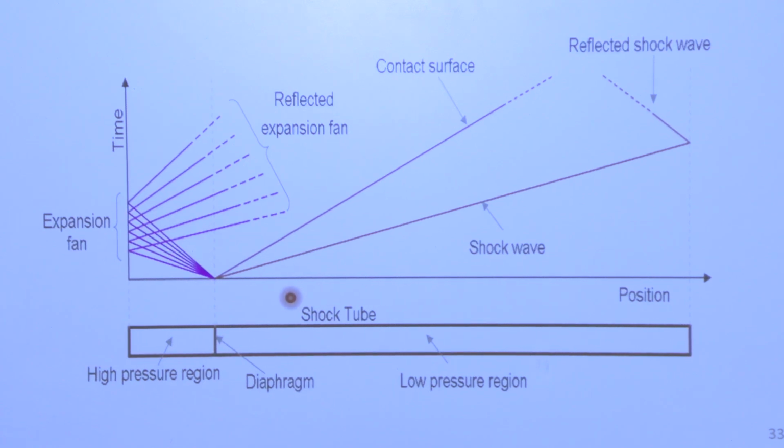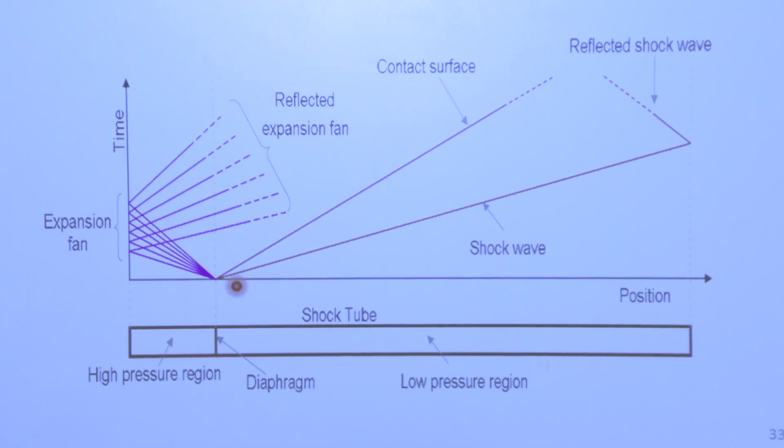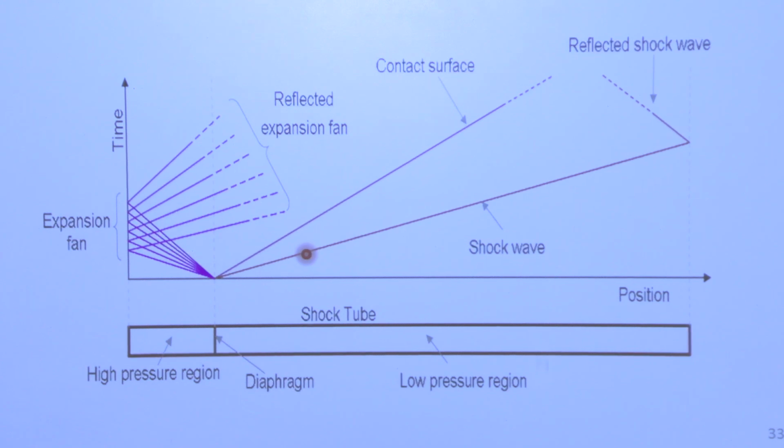The shock wave moves fast. It moves faster than the speed of sound. If you maybe take a shock class to learn about this, it's a little bit weird, but it does. And there's a formula that's called the CJ formula. It tells you how fast the shock will move. And so the shock is moving from where it started right here. It's moving down in position, and the y-axis here is time. So at different times, the shock front is at different positions along until it hits the end, and then it bounces back.